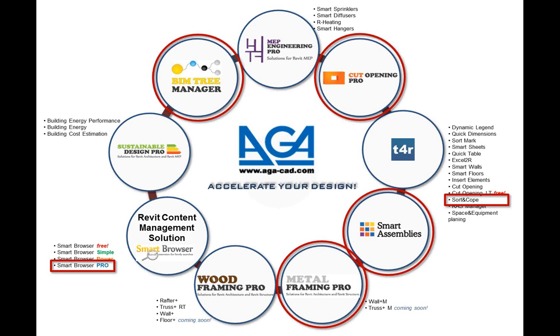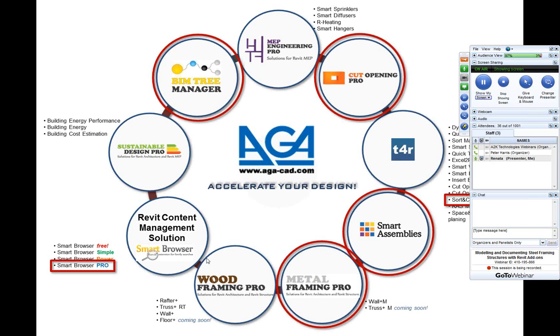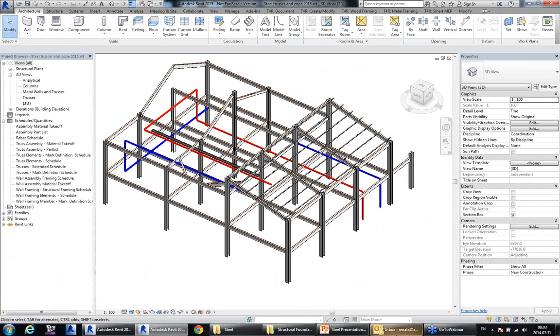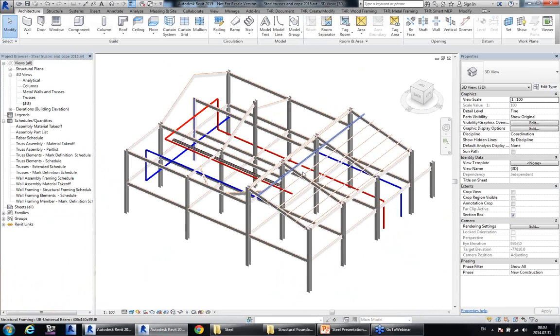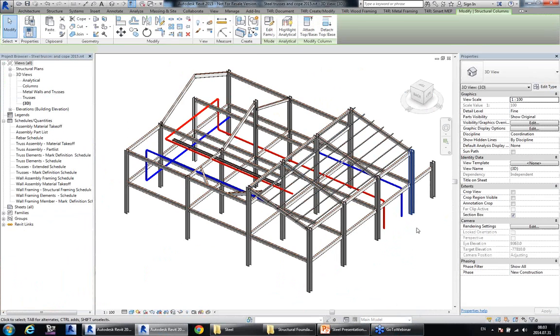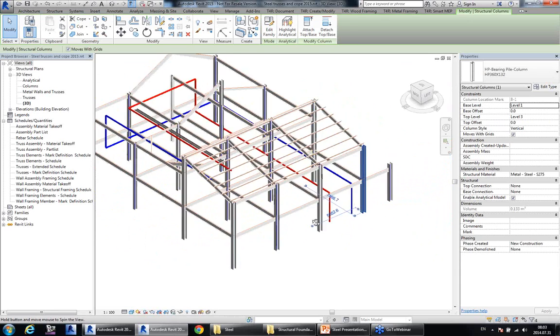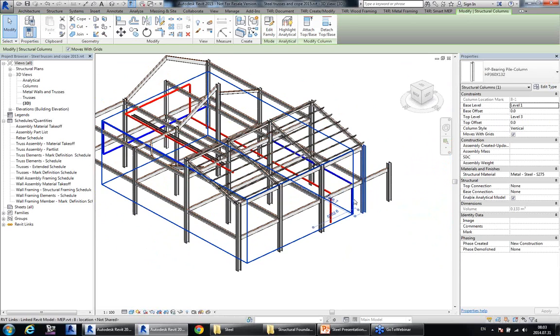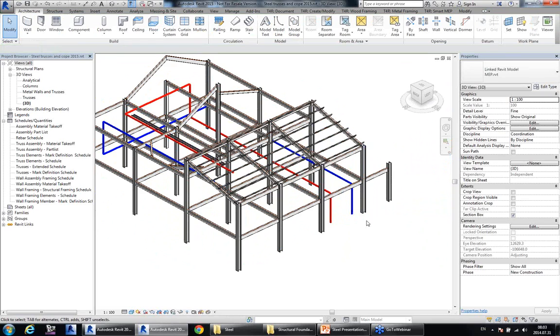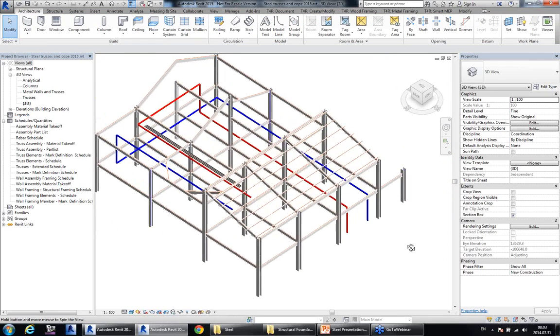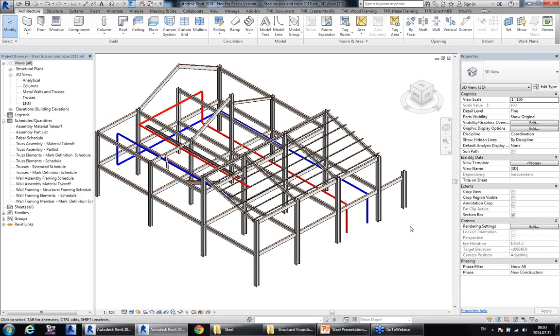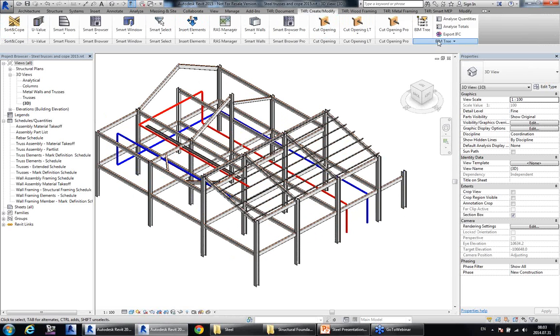Now let's go to the Revit project. Okay, and this is a simple model with several columns, beams, and with linked pipes and cable traces that come from the linked model. Now I'm going to start with distributing elements and with inserting foundations. And let's begin with BIM Tree Manager. That product you can find in the separate tab under the name Tools for Revit, Create and Modify.